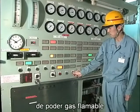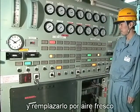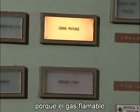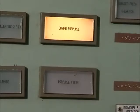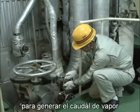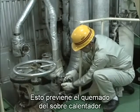Pre-purge refers to a procedure to purge flammable gas that might have been left in boiler furnace and replace it with fresh air. Insufficient pre-purge involves a risk of backfiring because flammable gas left in the furnace may explode when ignited. During pre-purge, slightly open the superheater vent valve to generate a steam flow within the superheater. This prevents burnout of the superheater.